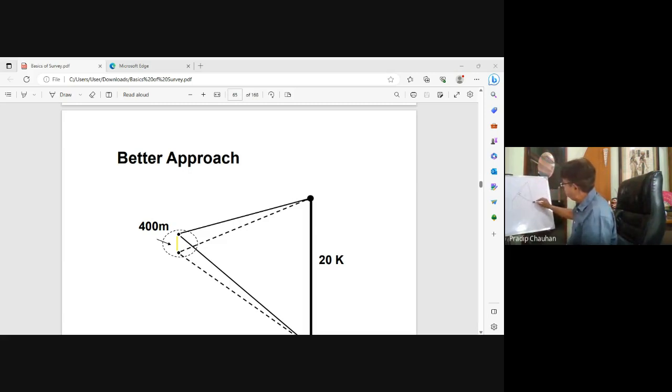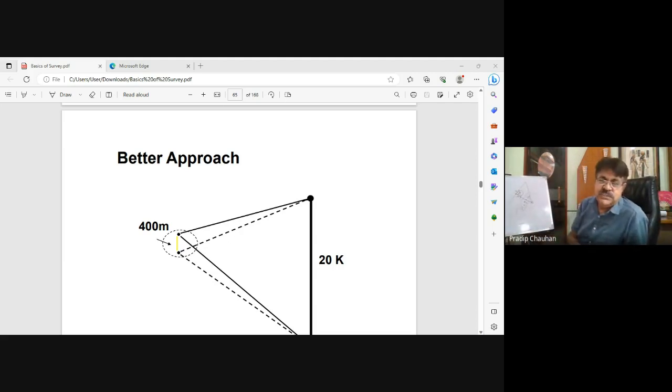If I need to reduce this point, from one side I will go 3 meter, and on the other side I will go 4 meter, in a way that I get 5 meter as my diagonal. Because by Pythagoras, the square of 5 is 25, equal to 9 plus 16; 9 is the square of 3, and 16 is the square of 4. So this is 3, 4, 5. We used this when we didn't have equipment for line out. It is the rule of 3, 4, 5, but this is the fundamentals.